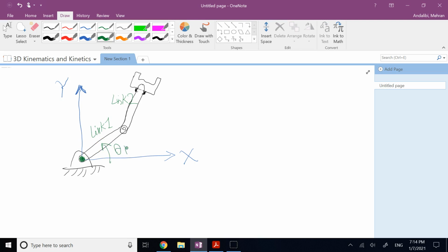right? But now, if you have another encoder here at joint 2, which gives you the rotation, what angle do you think it would give you? Well, it is measuring the motion between link 2 and link 1. So for it, link 1 acts like a fixed link, link 2 acts like a moving one. So what it really measures is not this angle theta 2, because it's measuring with respect to link 1, not the x-axis of the inertial system. So what it really measures is this angle. If you continue link 1, it is measuring this angle, the relative angle.